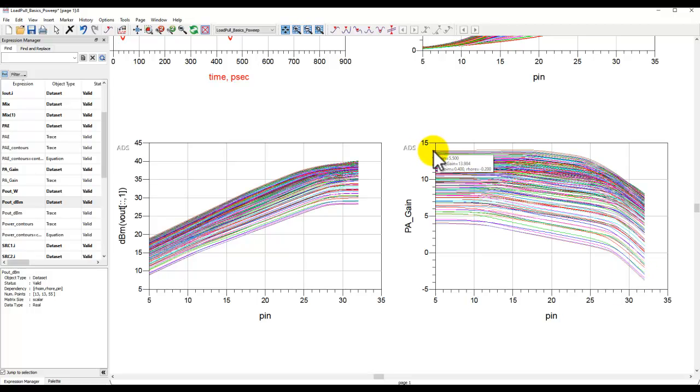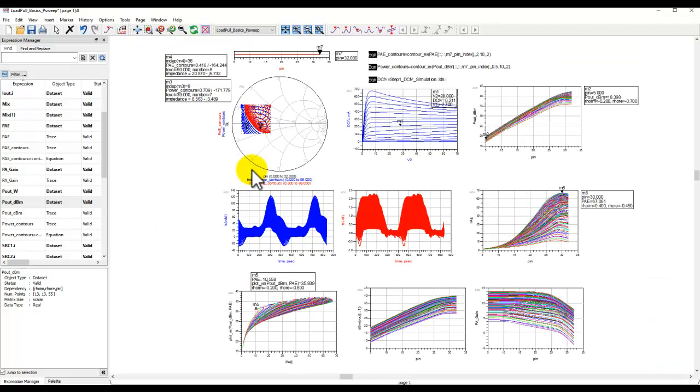Whereas if you look at this load reflection point curve, you are not that much into deep compression levels. So this is an important thing to remember when you are doing those kind of sweeps, because sometimes if you push your device into 10 dB compression, 12 dB compression during load pull, you may see convergence error. So you need to take appropriate precautions while doing so. All right, so this is the basic fundamental of doing a bit of advanced load pull.